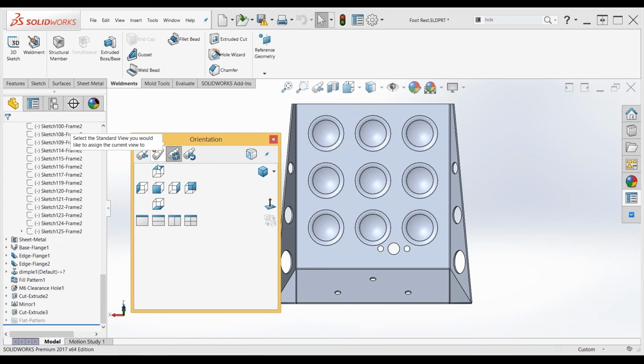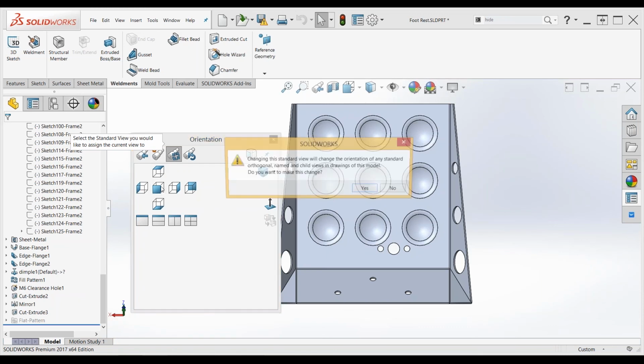Inside your drawing file, so I'm just going to delete these views now. They are not what I need. You can insert a drawing view that's relative to the model. So I click on that, and I get a little message here in my property manager saying select a planar face of a model in the graphics area of another window. So I'm like, okay, I got to change windows.